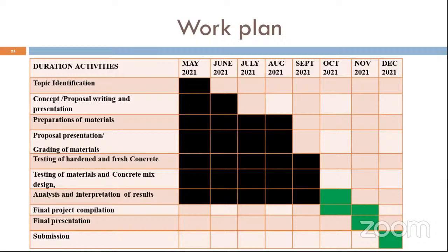But of course, you should know that concrete continues gaining strength indefinitely, maybe, but the gain reduces exponentially. So if you test concrete at 28 days and test it at 1 year, there will be a slight difference. But we are saying it has achieved the highest percentage, over 90%. So our target mean strength is expected to be achieved at 28 days.